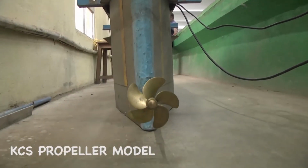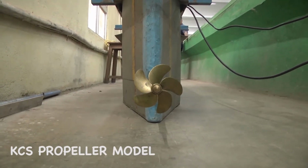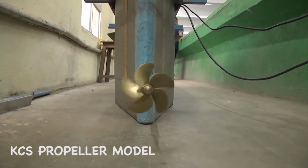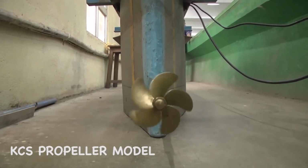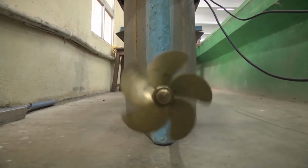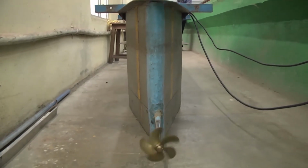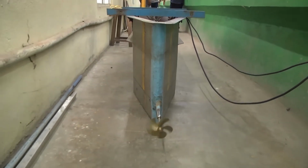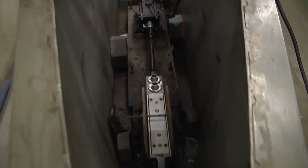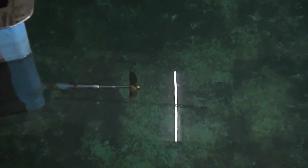Here is a short video of the propeller open water test. We have the KCS propeller model. KCS is a Korean container ship, and this propeller is fitted in front of the open water boat, and this particular part is shown out of water. So, we are just testing the propeller and shaft connections, giving a propeller RPM, and the motor and dynamometer are housed within the open water boat. So, here we have the dynamometer and the motor which are directly connected to the propeller shaft.